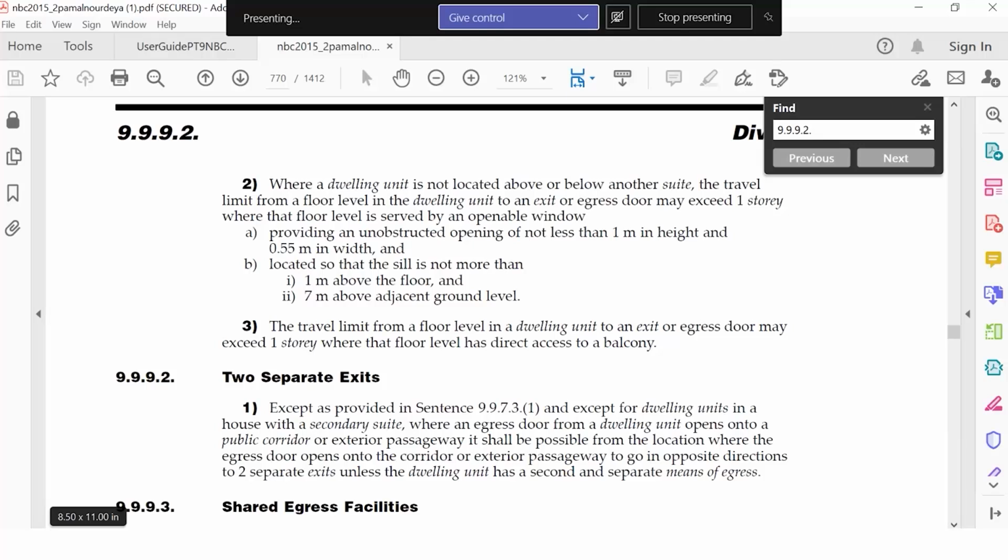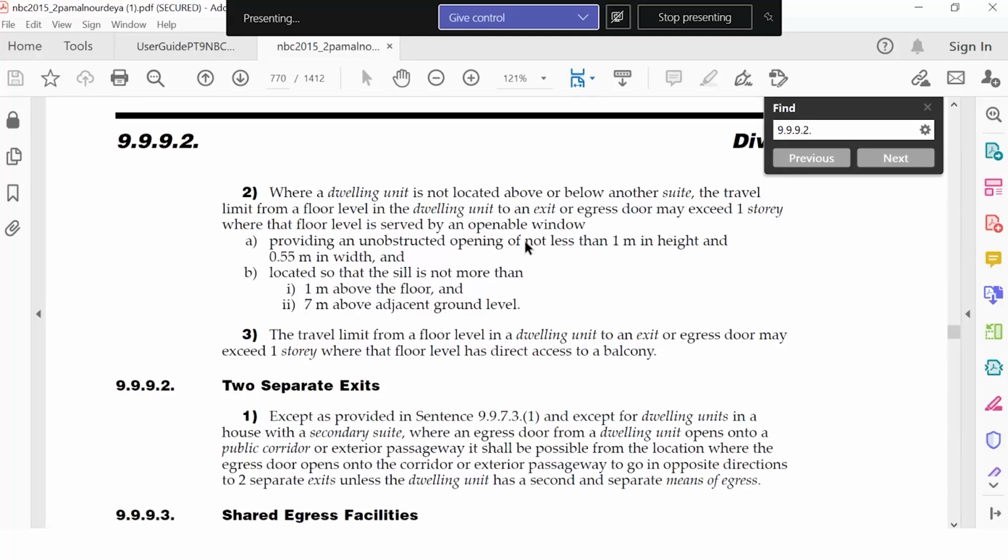Okay, so are you talking about party walls with fire separation of 1 hour versus firewall provisions? Exactly. So can you have 3 in a row just divided by party walls? No, that's when we're talking about the firewall separations.